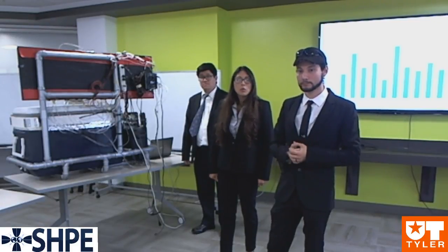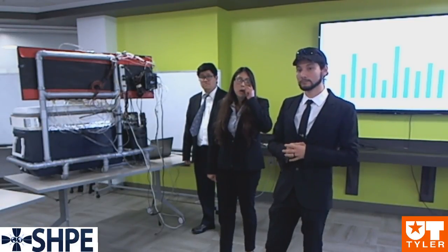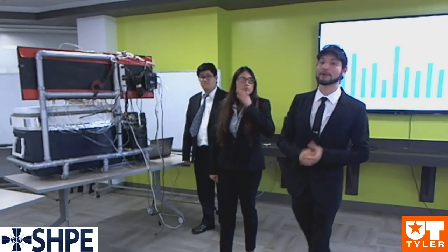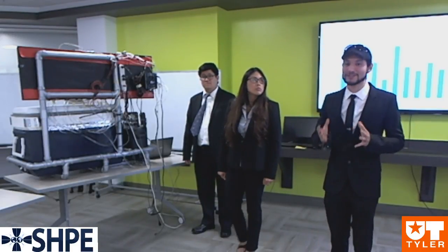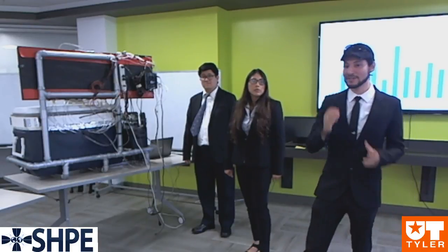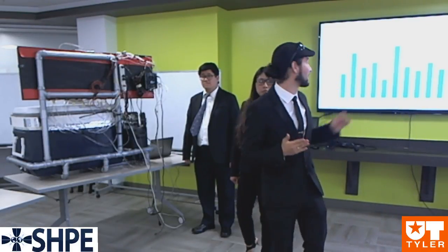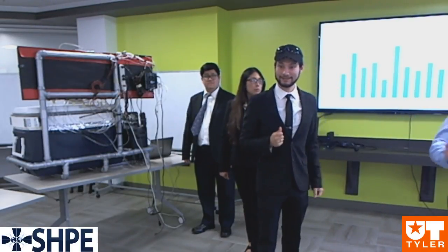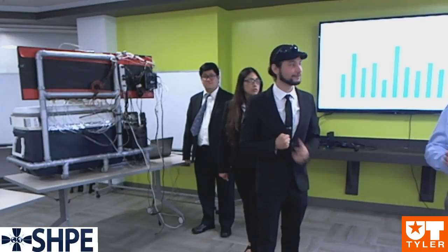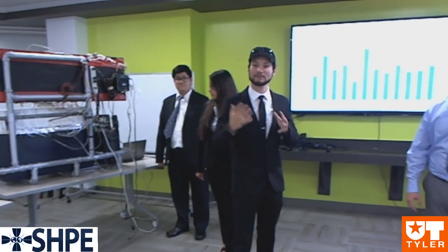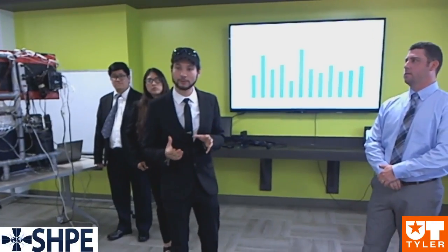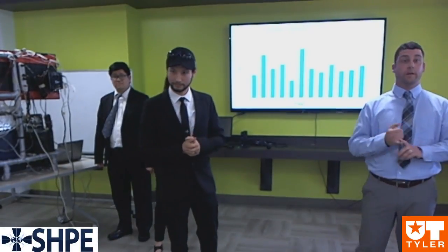So the water vapor displaces some of the CO2 in the atmosphere, is what you're saying? Basically, no. What I'm saying is the flow gets restricted, so the sensor picks up this change in flow as an anomaly. I think we're going to walk back on the statement that a clog causes excess or decreased CO2. That's not correct, and it's because the sensor is very sensitive to the flow of air. Could excess humidity throw off the sensor?